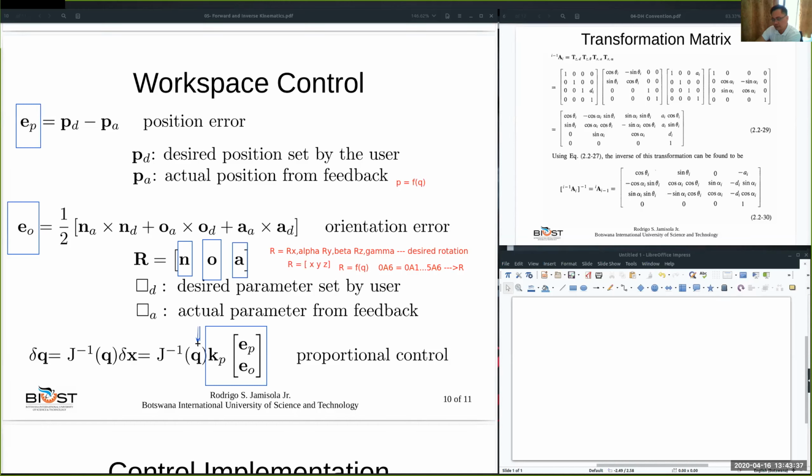This is the current Q. Now from this current Q, you also have the current position and orientation from this error term. Then you compute that. Now it will give you the new desired step that you need to do from the current joint values that you are given. So now that completes our control equation.